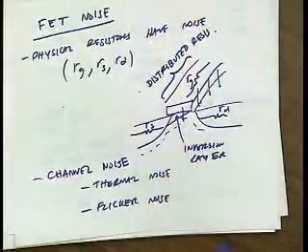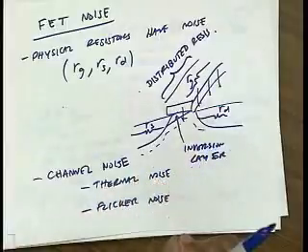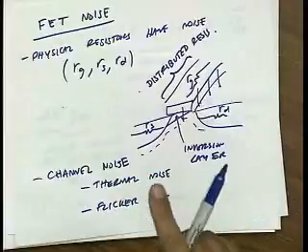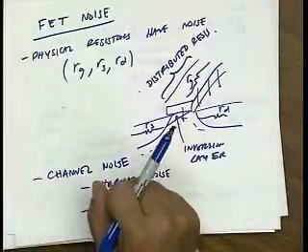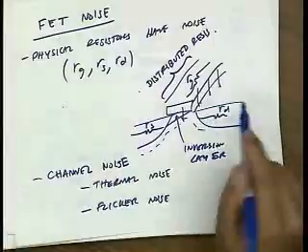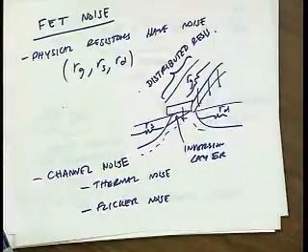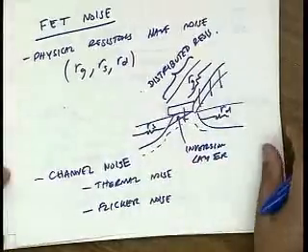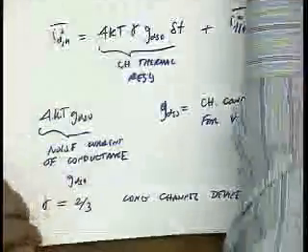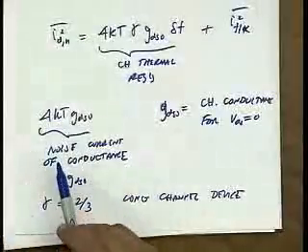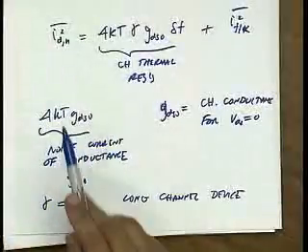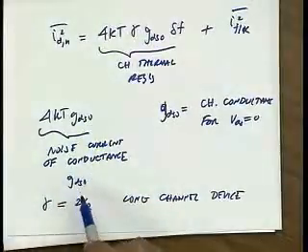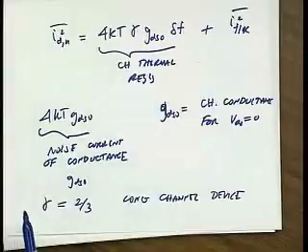And you say each tiny little piece looks like a resistor that generates noise 4KT delta G, where delta G is that tiny little resistor. And then you integrate over all those tiny little resistors to get the total noise current, assuming that they're all acting independently of one another, which is somewhat of an assumption. But at the end of the day, you end up with the total noise being 4KT, the sum of the little g's, and you know the sum of the little g's is GDS0, and this extra factor 2/3. Okay?